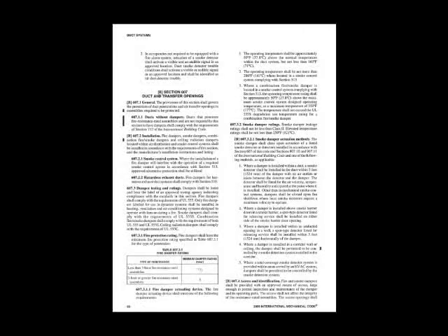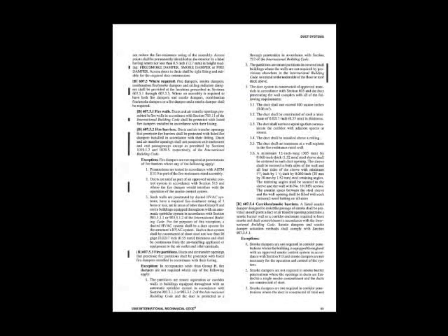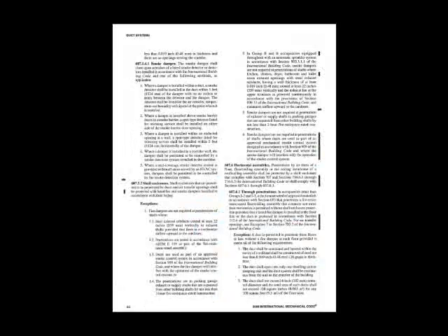Section 607 talks about duct and transfer openings. It talks about ducts with dampers, how we have to have smoke dampers in certain places, and how smoke dampers work, 607.3.2. Section 607.5.4 talks about corridors and smoke barriers. It gives you a whole bunch of examples in terms of where smoke detectors and dampers are required and where they are not required. Section 607.5.5 talks about shaft enclosures, horizontal assemblies, and penetrations. And 607.6.2 talks about membrane penetrations for roofs and ceilings.